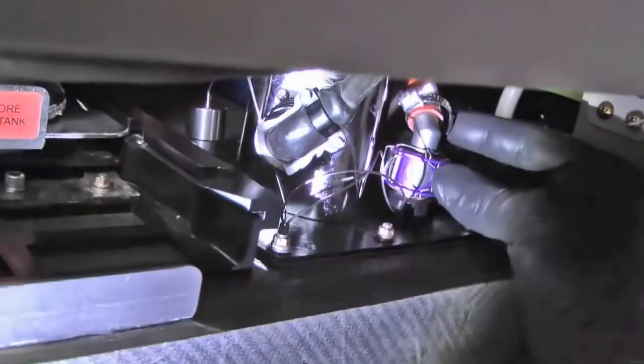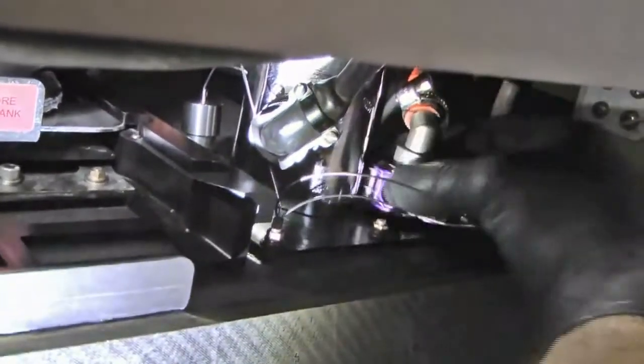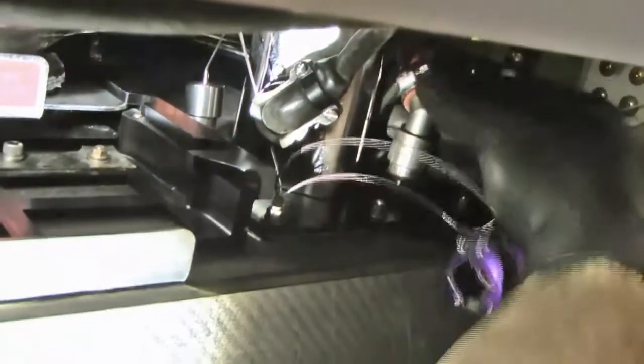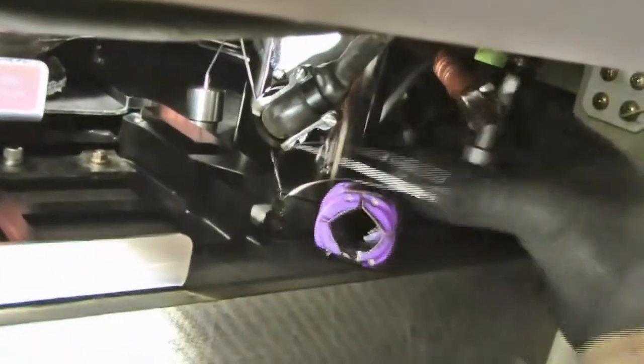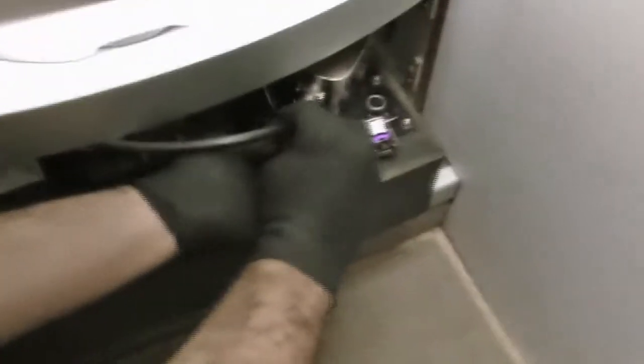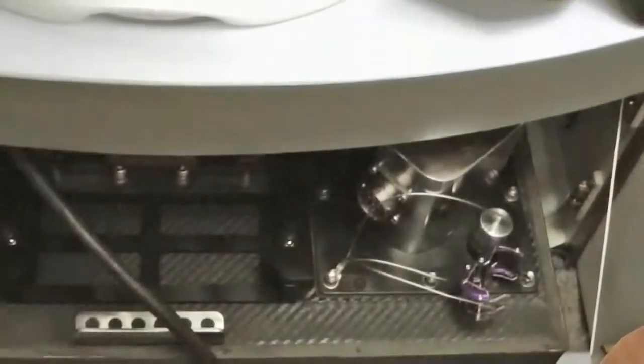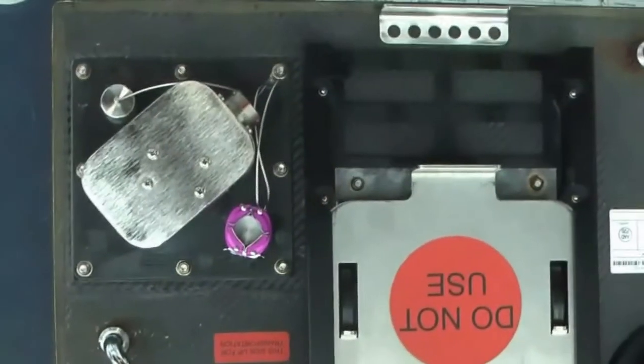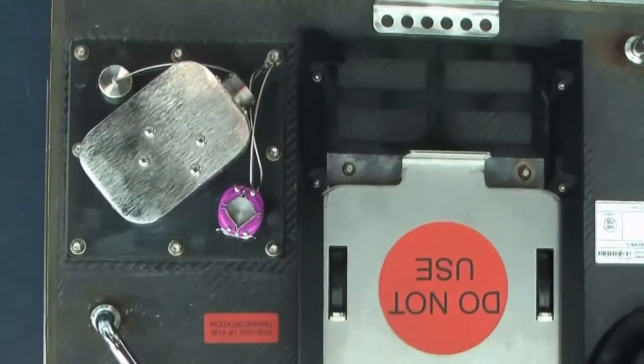Unlock the latch that attaches the waste tank to the toilet shroud box. Loosen the clamp and remove the clamp from the flush hose. Remove the flush hose from the hydraulic connection. Disconnect the electrical connector and put a protective cap on it. Disengage the hydraulic protective cap and put it on the hydraulic connection. Put the clamp on the hydraulic protective cap and lock it.